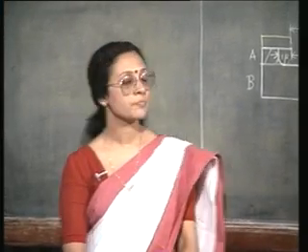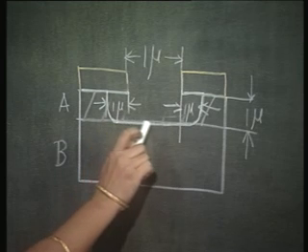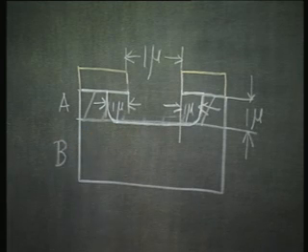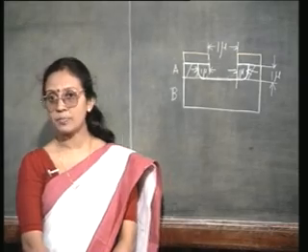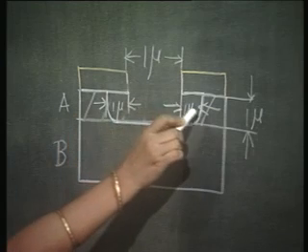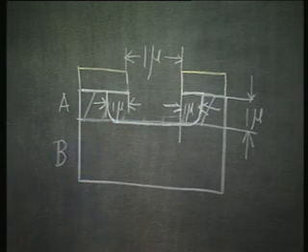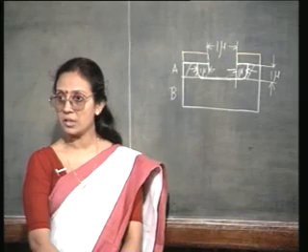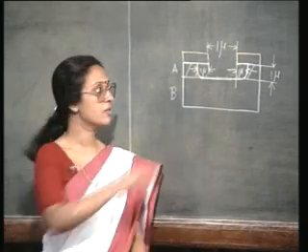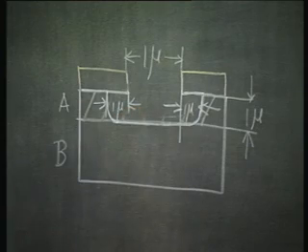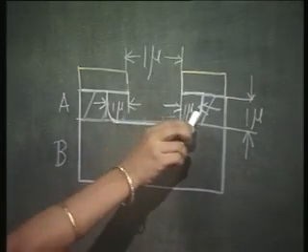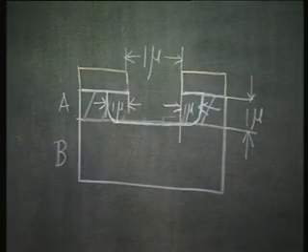So, what happens? From the instant I have reached the interface between A and B, the etchable surface is only the sidewalls. It does not etch B. So, the etching virtually stops here, but it can keep on etching the sidewalls.